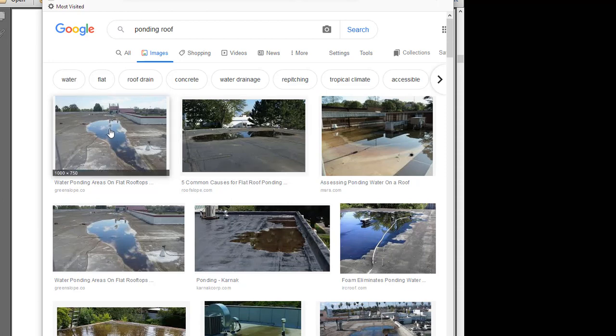And as the roof deflects, more rain and more water is now going to collect in that dip that's caused by the deflection of the initial rain load. And so as it deflects, more load collects, and then it deflects more, and then gathers more load, etc. And sometimes this can lead to collapse.